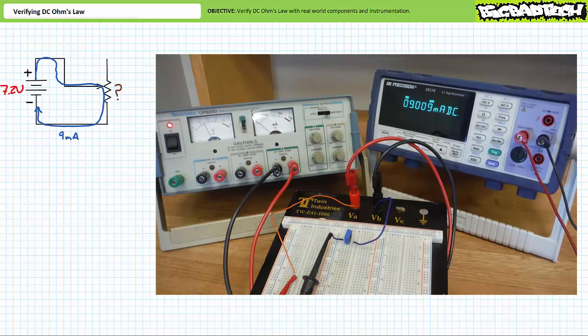What did I do to the potentiometer? Did I increase or decrease resistance? Think about it. No numbers. Voltage stayed the same and current decreased. Did resistance or opposition to current flow go up, go down, or remain the same? If you're tracking, you should realize that resistance has increased.